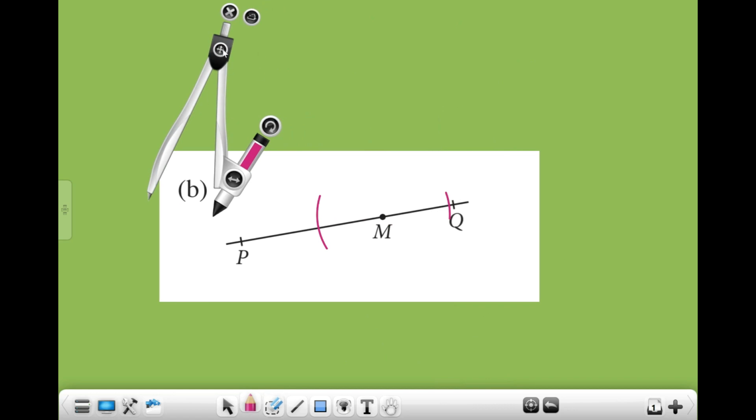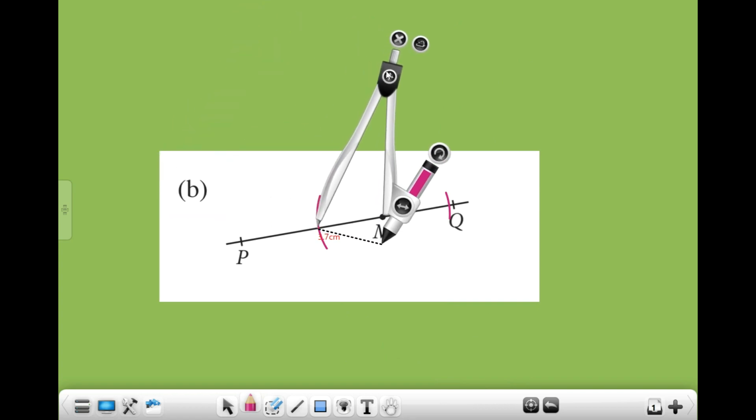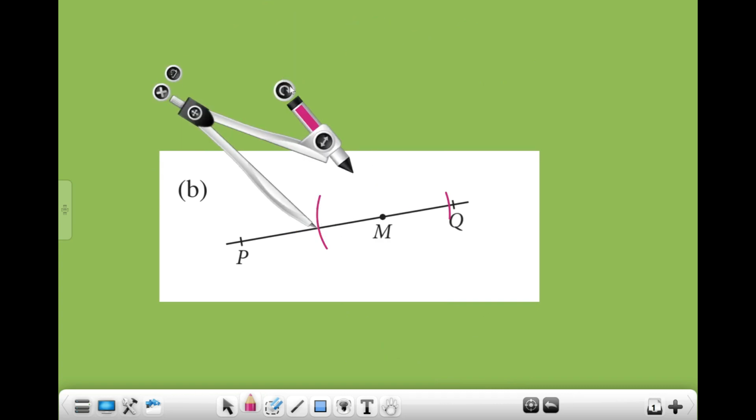So now this is your line segment. Always remember when you have cut on both sides, this is the length of your line segment. So we are going to use this point over here to continue with the construction of the arc on top. And we have this point as the guidance already, so you don't have to do it on top and at the bottom. Like what we had earlier, the perpendicular bisector, if you're given a straight line like this, you have to construct the arc above and below, and then you move to this point and construct the arc above and below, so that you can join these two intersecting points like this. But right now, for this diagram over here, because you have point M as the guidance already, you only need to construct another arc above or below, either one only. But if you construct both, no problem, it's still considered correct. So now I'm just going to draw one on top only.